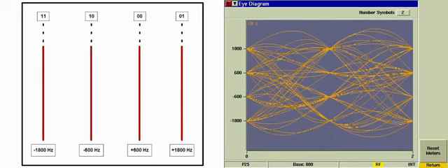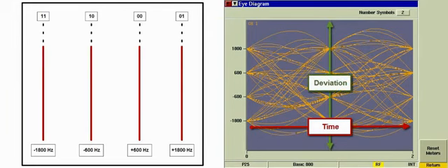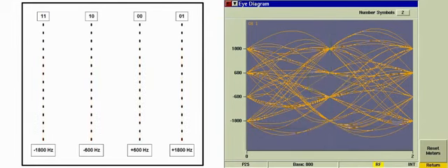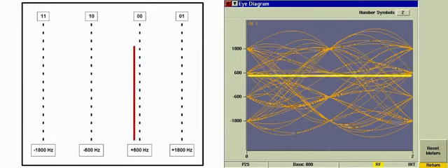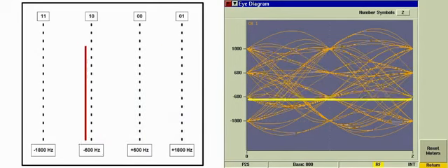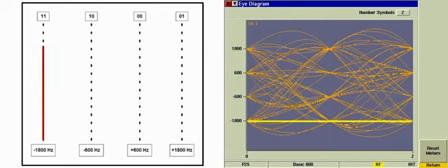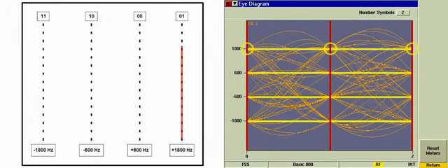Whereas the constellation diagram and distribution plot show the demodulated signal at the symbol points, the eye diagram displays the demodulated signal at all points. The horizontal axis of the eye diagram represents time. The vertical axis of the eye diagram represents deviation. The four horizontal dashed lines represent the deviations at the various symbol points. The vertical lines and the start-stop of the graph are the locations at which the graph goes through a symbol point.